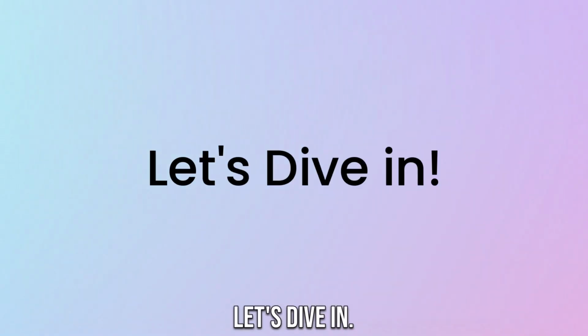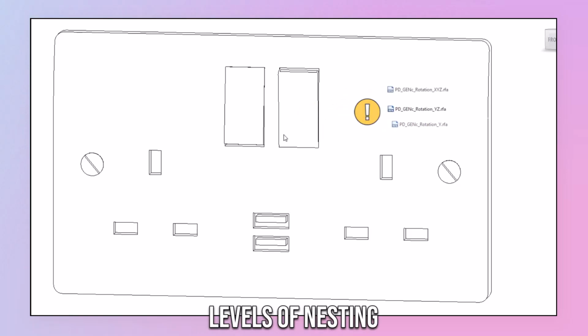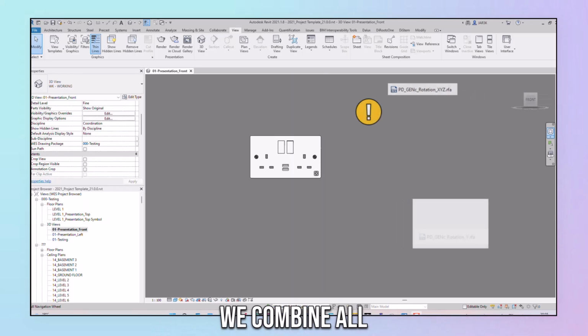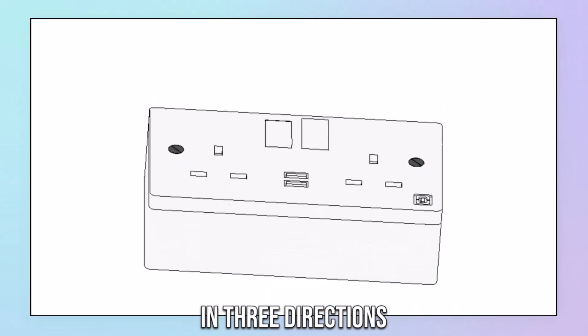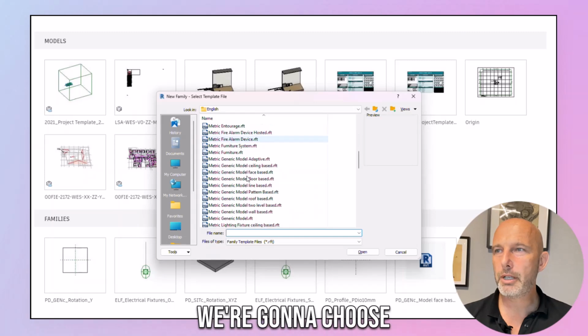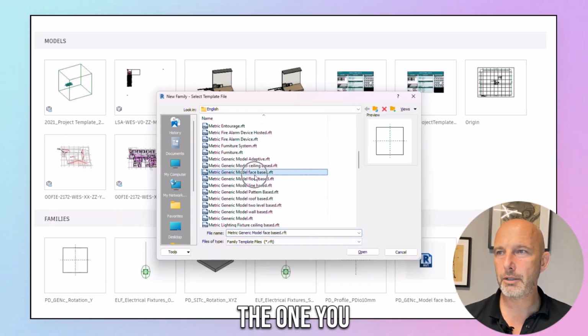Okay, let's dive in. To make the host, we're using this Revit function of nesting families within. We need 3 levels of nesting. At each level, we're gonna rotate 1 axis. When we combine all of them together into one final family, then we can rotate the host in 3 directions. You need to go and create a new family, and we're gonna choose metric, generic model, face based. That's the one you need to choose.